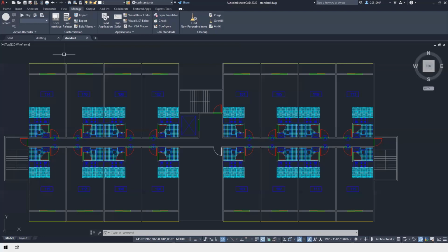You may be wondering what the difference between a CAD standards drawing and a template may be. Templates basically have all the settings that you need for your drawings, whatever it may be, and you load the template and you have those default settings. Those settings in your template can be modified and changed unless there is a standards file associated with that template. You can convert a template into a standards file as well, so you could actually use a template that enforces the standards as you're working.